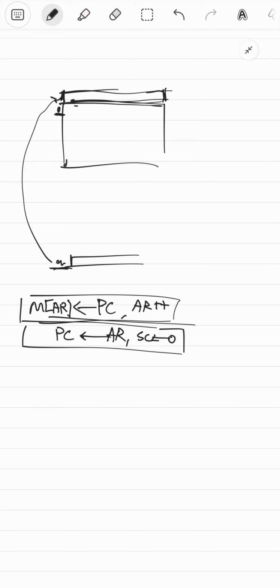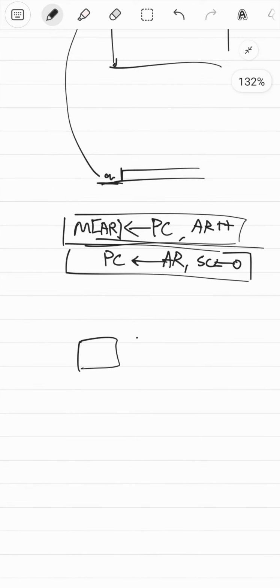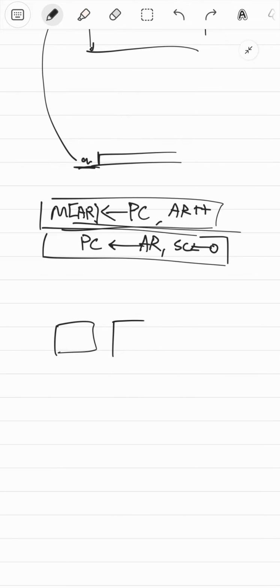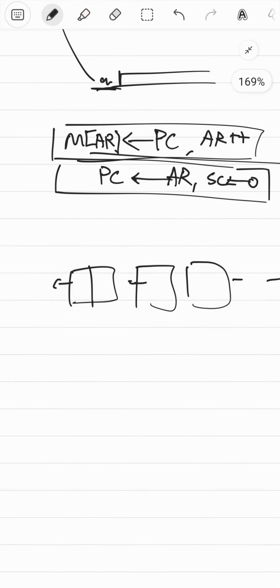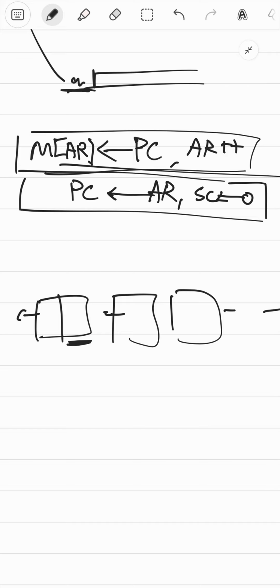Okay, how do I exactly explain what's going on? So you remember how a counter works, right? A synchronous counter. So you just have these D flip-flops. It has some values coming out of it. And every D flip-flop is actually 2 D flip-flops. So you have something that only accepts stuff at the negative clock edge, and something that transmits stuff at the positive clock edge, right? I'm just going to shade this as black, so that you can think of it as, this part will store the value at negative clock edge, right?